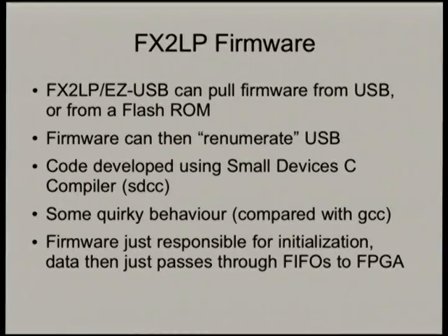So firmware can then renumerate the USB, so it basically shuts down USB and starts it up again, makes it look like you've just unplugged it and plugged it back in again, but now it's got a new vendor ID and device ID, and this time it should trigger the kernel to bring up the USB network device driver that you've loaded. So the code for the 8051 is developed using Small Devices C compiler, SDCC.